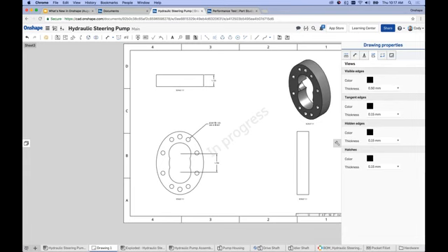The ability to adjust line thickness was a commonly asked question that we just couldn't do in the past. We now can. And also the ability to adjust color of things like dimensions and so on. That was, again, a limitation. So this drawing properties flyout solves a lot of those individual questions about how do we change color, how do we change thickness, how do I change those kinds of details.